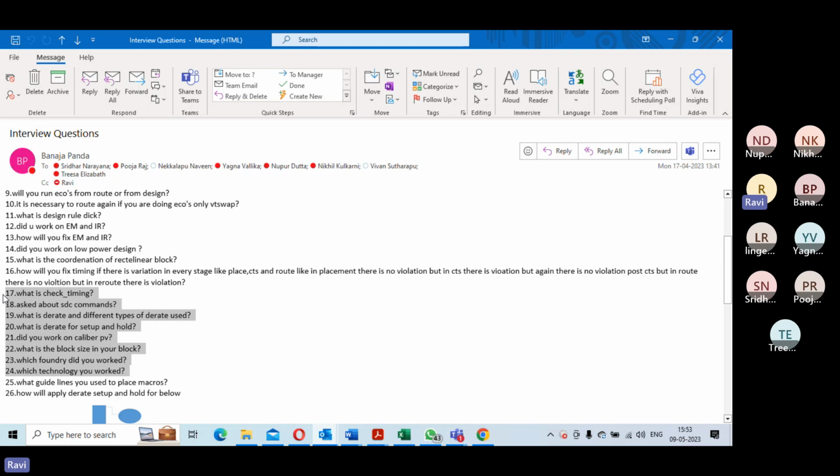From a physical design point of view, as I told you, you can give constraints like max tran, max cap, max fanout, and also what kind of cells to use, set don't touch, don't use. All these are design level constraints that you can specify. Then exceptions, that's another category.